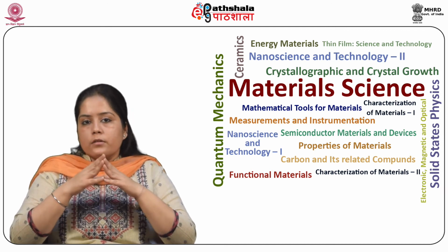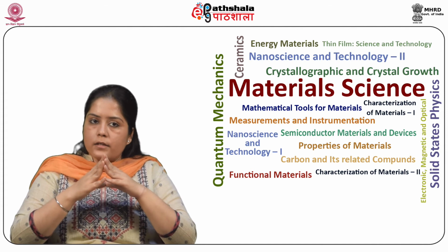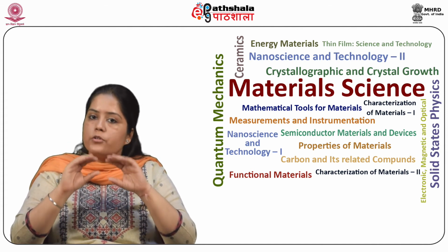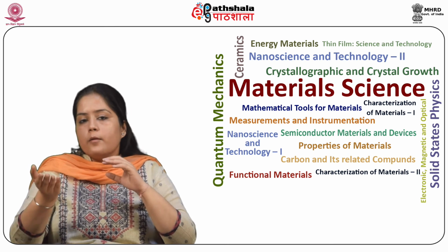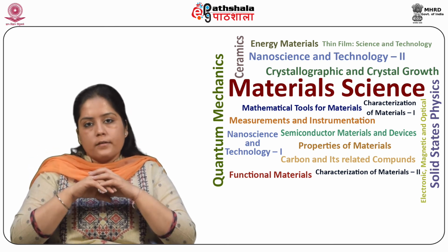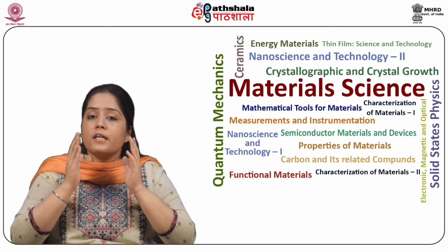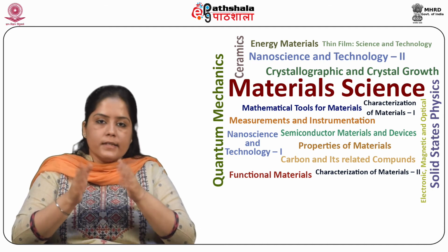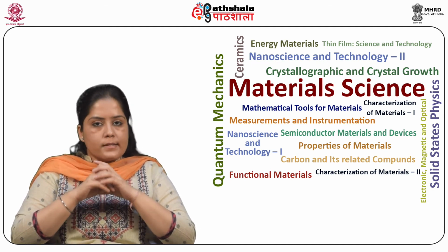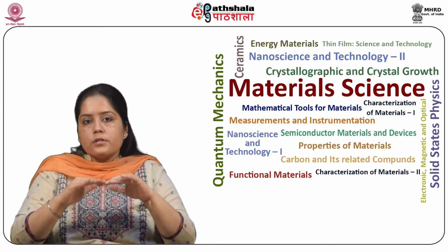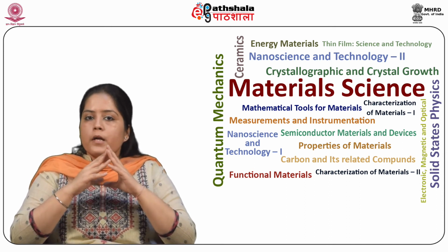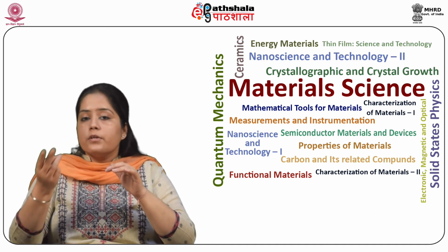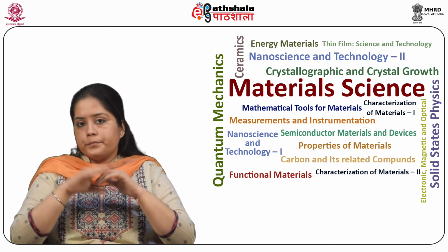In addition, one can add a small amount of manganese and aluminium, say up to 0.5%. The advantage of these alloys is that they reduce the power losses in transformer cores by a factor of 3 or more.